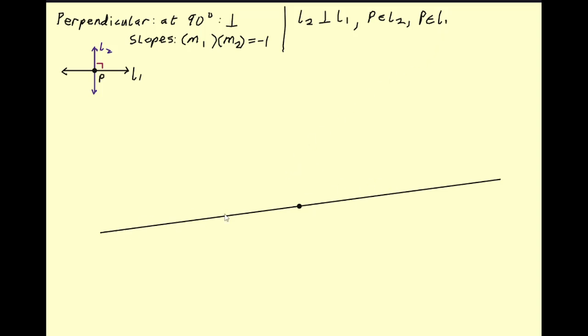So that is our setup. This is our original line, and this is going to be our point, and we want to get the perpendicular to this original line going through this point. If we think about perpendiculars to lines, where we've come across that concept before is with a perpendicular bisector of a line segment, and effectively that's how we're going to construct this. There are technically two ways to do it, and we're going to look at both of them, but the most important one is what links to more broadly what we already know. So we're going to look at our construction where we are effectively just doing a perpendicular bisector.